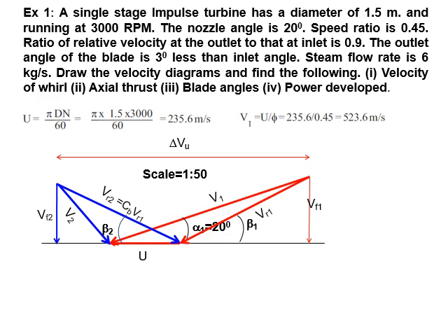Then measure the delta Vu. In this velocity diagram, what does delta Vu represent? It is the summation of Vu1 plus Vu2. That is, Vu1 plus Vu2 is equal to delta Vu on this velocity diagram. And also find the alpha 2 angle.